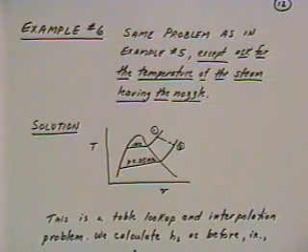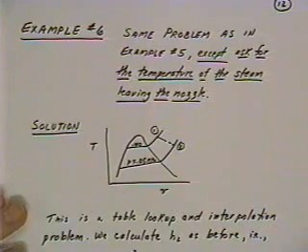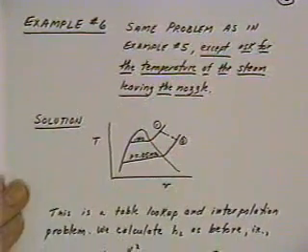That's something that you have to get out of the steam tables. We know that the temperature is going to drop a little bit just as the enthalpy drops. The temperature is going to drop a little bit as the steam leaves the nozzle. We found the enthalpy, so we can use the steam tables now to go back and find out what the temperature is of that steam leaving the nozzle.